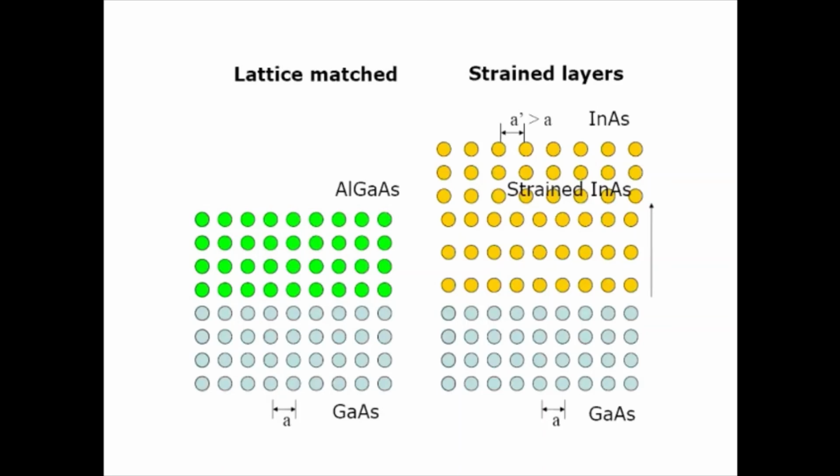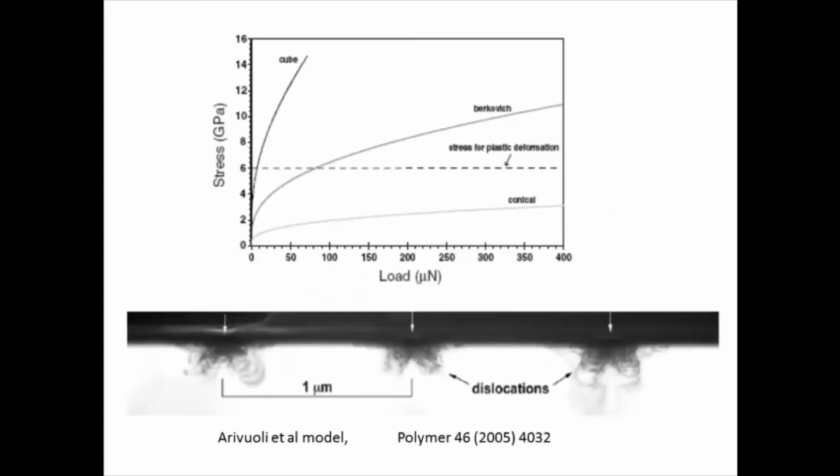If you consider gallium arsenide and aluminum gallium arsenide, there are different device structures which can be grown using MOVPE or MOMBE, right? So here, we have done this. We made various indentations on the substrate using a nano indenter. So these are all the indented portions to a particular depth using a nano indenter. And when you make an indentation, what happens is that you are straining that portion.